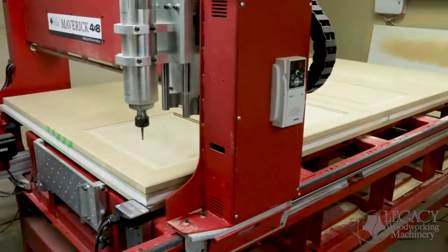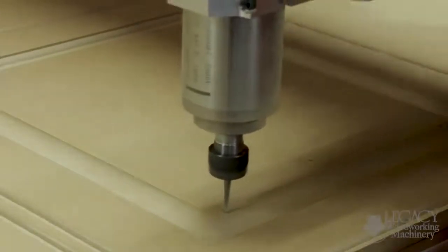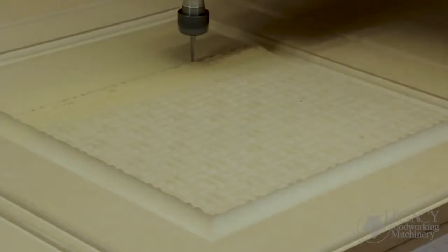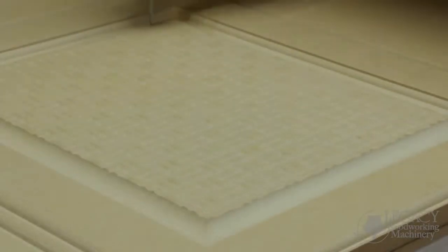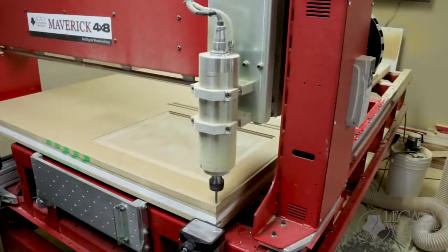The third textured panel will be using a tapered ball cutter that has an 1/8 inch ball nose. This will simply raster back and forth to give us the detail of the weave. Even though this texture is captivating, it took over 2 hours to carve that textured panel. The last cutter is a 1/4 inch end mill and is used to cut out the doors.